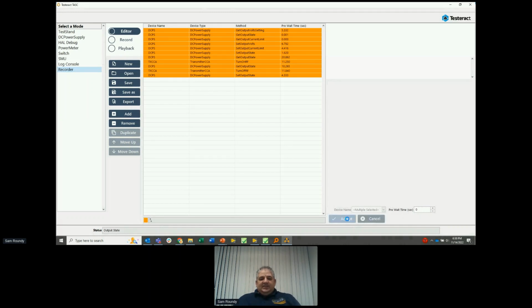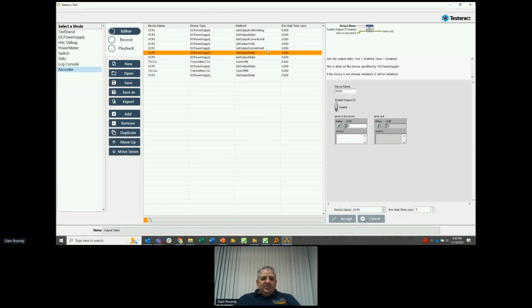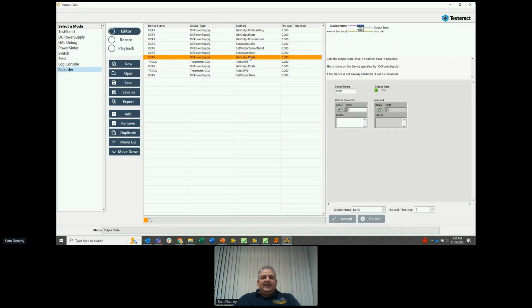You'll see it will set that pre-wait to 0, but maybe there's some steps that you do want some wait on. So let's say that we want to set the output state to, where is it? Right here. Let's say that before we get that current, we want to wait for the DUT to boot up, right? So we might put a 2-second delay in there. And then we want to turn it on. And then before we get the current again, we want to put another 2-second wait in there. And so we've got these 2-second pre-waits, but the rest we don't care. We want it to just fly through that stuff, right?